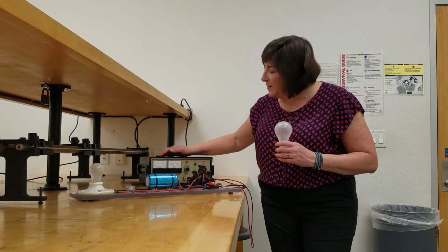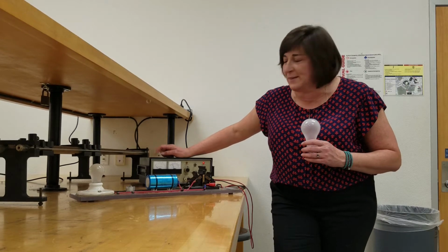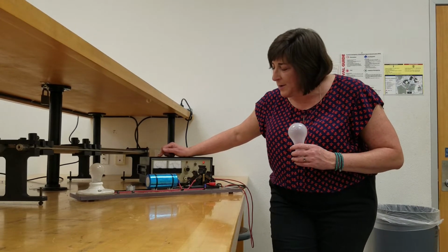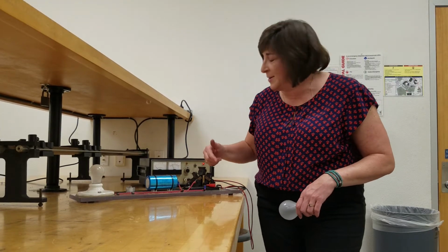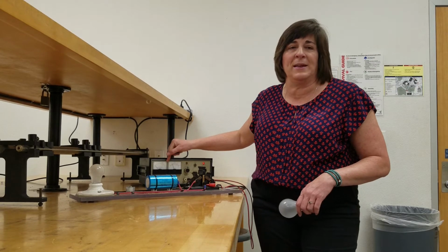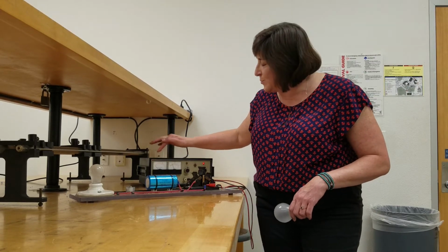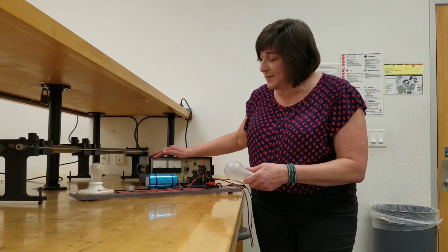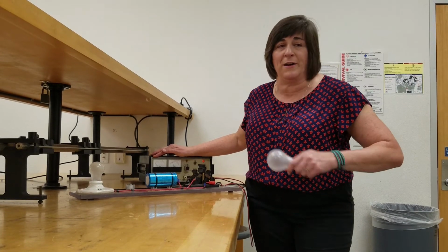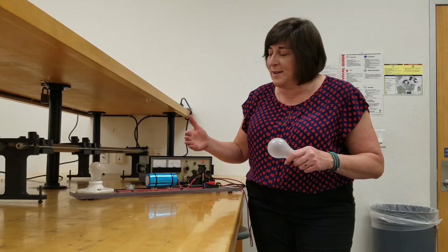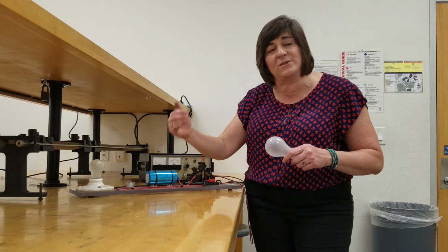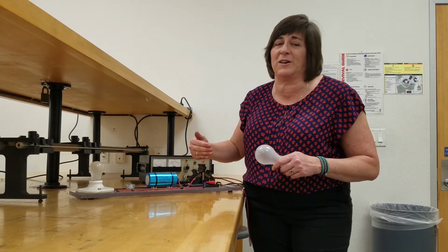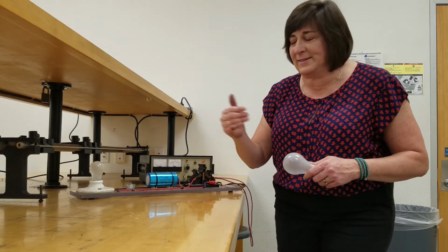On my meter here, the meter on the left will show me the current as a function of time. So right now what I'm going to do is connect the capacitor to the battery itself to start the charging process. You'll see the current jump up and then slowly go down, because right when we first connect the capacitor to the battery, charge will flow very quickly, but as we build up charge on the negative side of the capacitor, it'll be harder and harder and harder to force more electrons onto that negative side. And so the current will go down exponentially as a function of time.